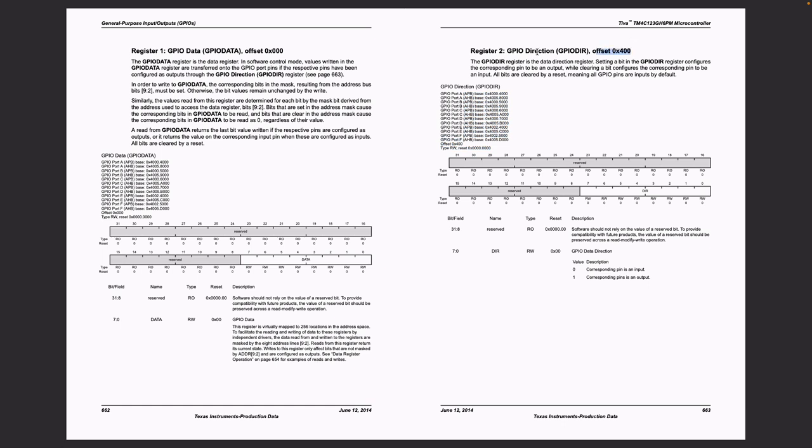We will point to this register, the direction register. What this datasheet is telling us is we have 8 bits available to configure our port, and each of these bits represents one input or output that we have available.